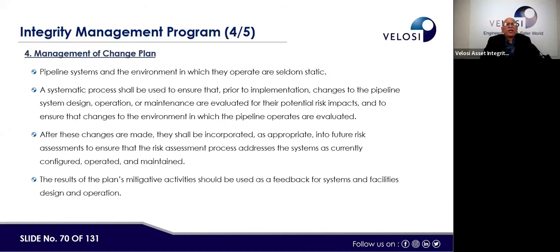For example, if there is any change, it's the management of change procedure. It has to be followed, so if any change in the system is required, it should be done by following the management of change process. In that process, whatever due studies, cause and effect, root cause analysis, or engineering and process analysis are required should be done, so that any change is not done as a shortcut, and no detailed analysis is missed.